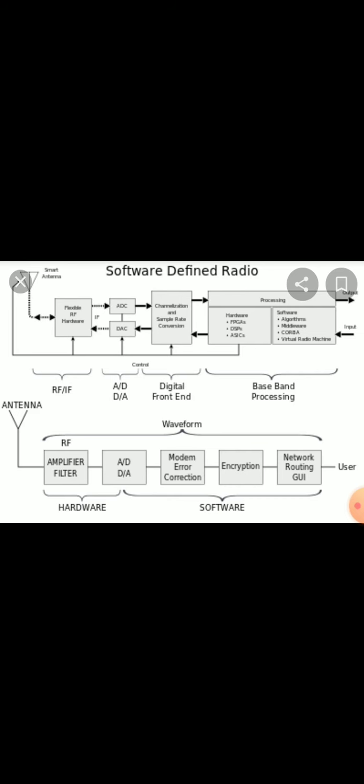So SDR is a radio communication system in which components like mixers, filters, amplifiers, modulators, demodulators and detectors are implemented by means of software on a personal computer or an embedded system. This is the software defined radio platform.